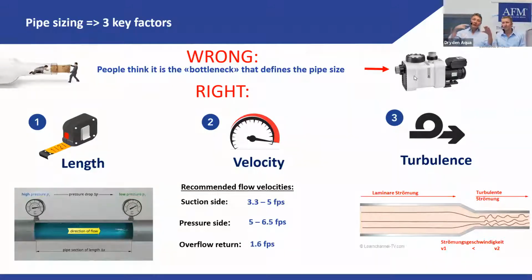Yeah, because in a straight pipe, you have some friction and with this pressure drop, but if you come into a fitting, 90 degree and T, etc., you get a high turbulence. And so the more turbulence you get, the higher is your pressure drop. And that always goes together with the speed. So the speed is important for the length, and it's important for the turbulence.